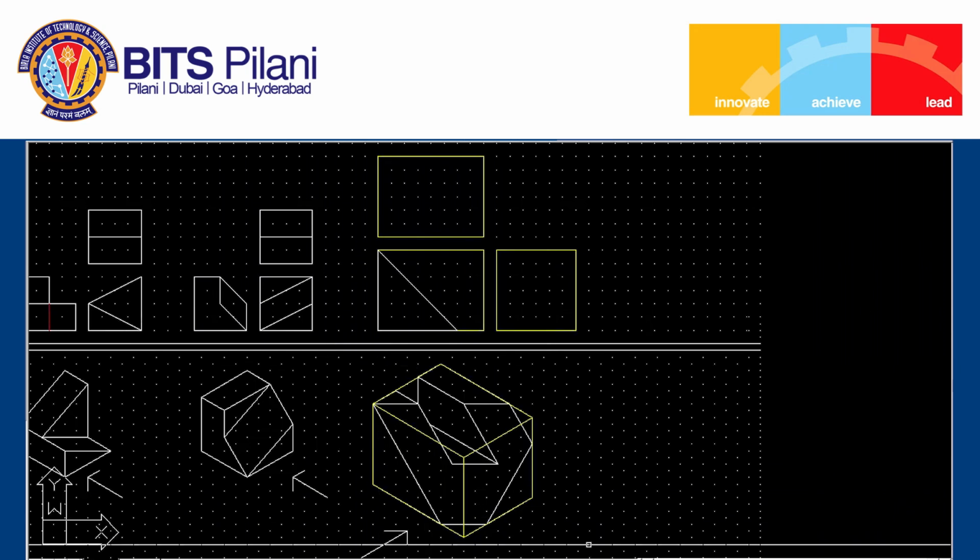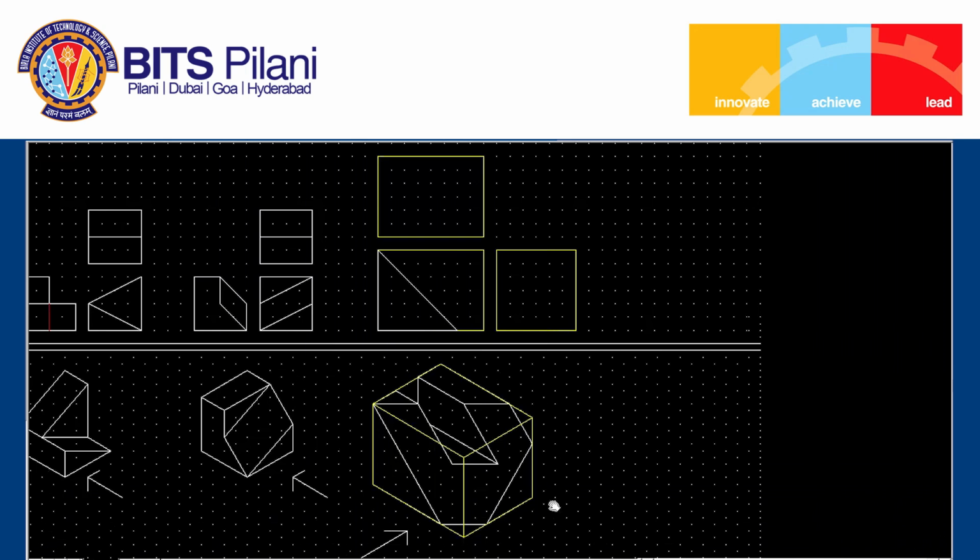Then if you see this principal surface, it will fall into a line view. These two principal surfaces will fall into line view. So, what is the length of this principal surface? It is 2 grids. For this principal surface, it is 6 grids, that we can see. So, what we will do? We will try to first draw the top view and then again come back to the front view. Otherwise, I can directly draw the front view also by identifying the corners, but from the top view it will be easier for us. So, we will draw these two principal surfaces.